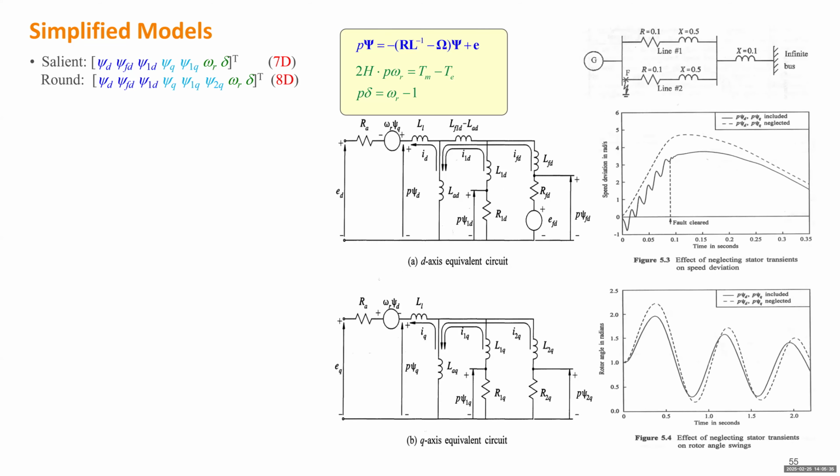Then the next step. This one represents the test, because in this model, there are 2 flux linkages for the stator, a psi_D and a psi_Q. But in those circuits, we know for steady state condition, it is equivalent to a short circuit between those 2 points. Because this is actually the major source changing the power output from the generator. Not those others, which only determine dynamics in transient or sub-transient dynamics. Similarly, under steady state condition, those two will be directly connected, so those will not influence the power output much. Okay, then we can do a test. We just add a disturbance at the terminal of the generator, and we compare the two models.